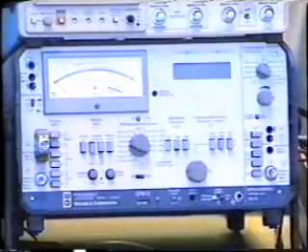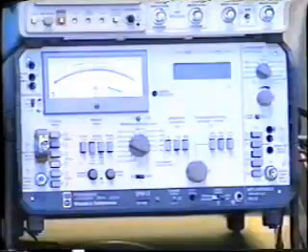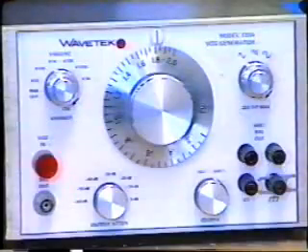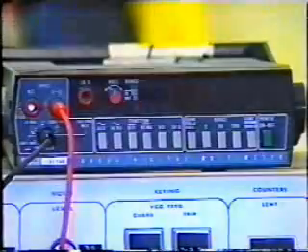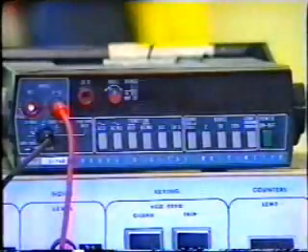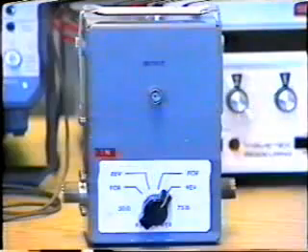You have observed that specific test equipment is required for setting up carrier systems. The essential devices are the frequency selective voltmeter. This registers the signal at the selected frequency only and disregards all other signals. The signal generator to provide a test signal at selected frequency. The RF voltmeter. The frequency counter. The reflective power meter.